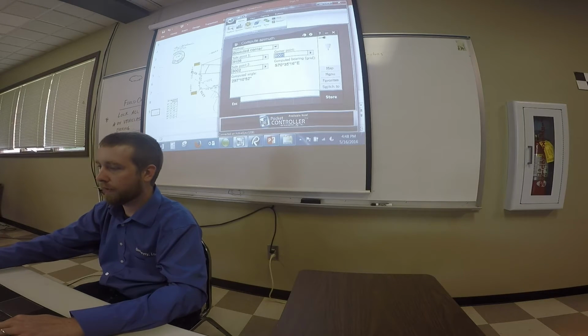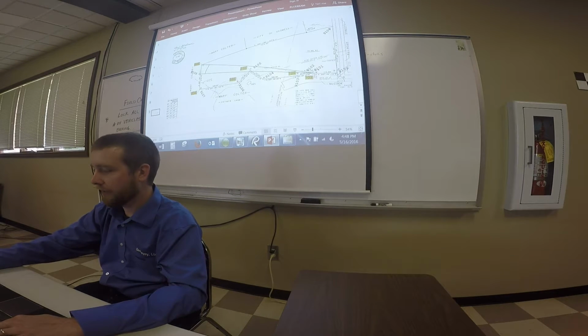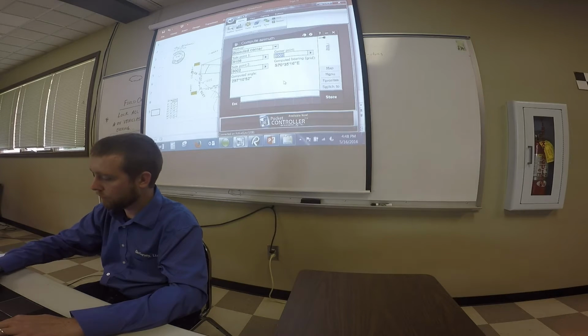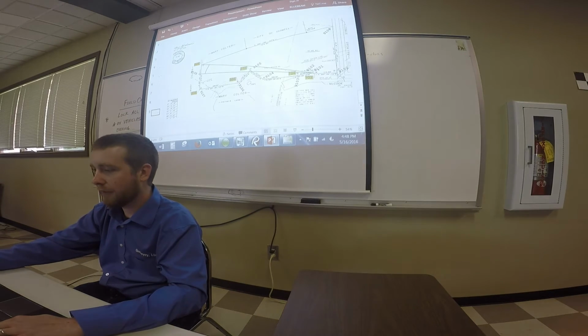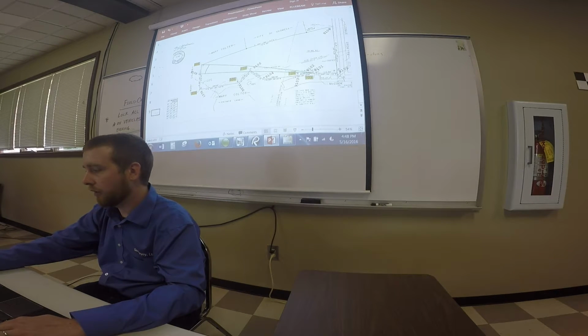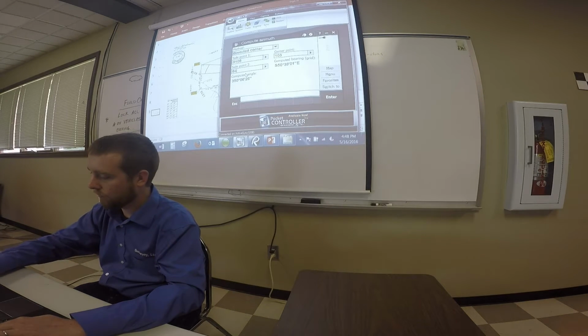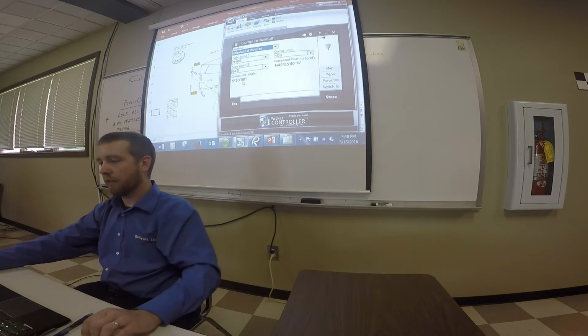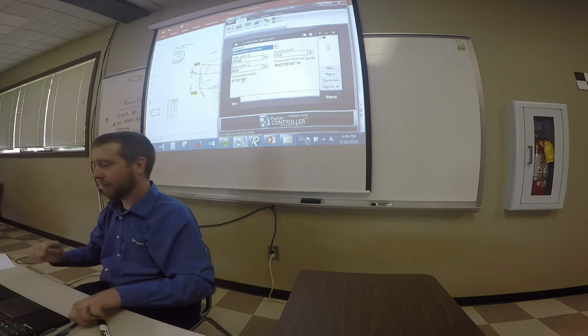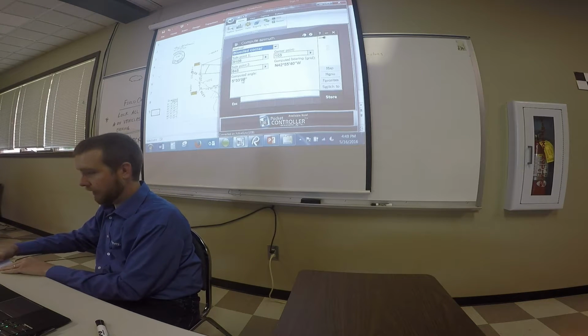Our corner point is 103 down here. We already moved it. Side point 2, so this is 1, here's our corner, here's 2 up here, 845. 5 degrees, 33 minutes, and 8 seconds. And then that'll be the angle we're going to rotate.